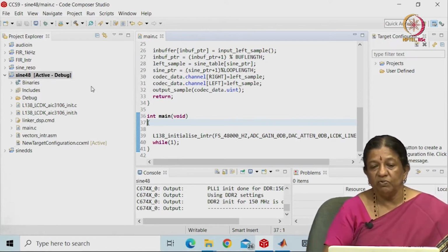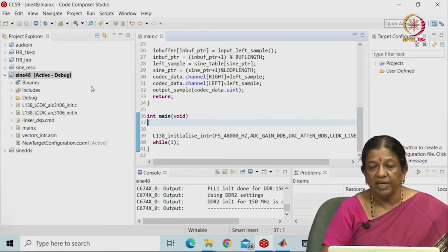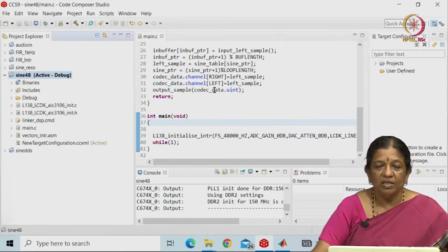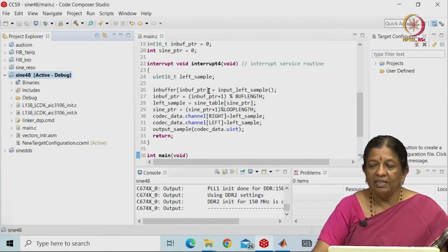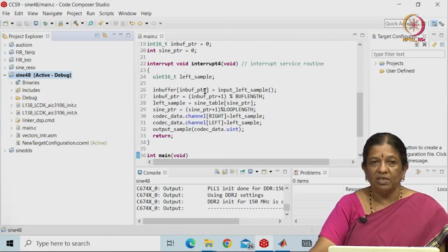As you can see, I can disconnect my laptop; I only need it for the debugging session. The code is loaded onto the board, and then it can run continuously. Here there are 48 samples, and the code is going to live in the board. So unless I reset the board, it will be running continuously. This is what we call real time.